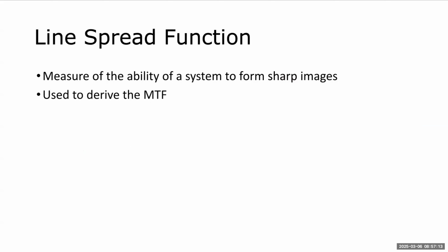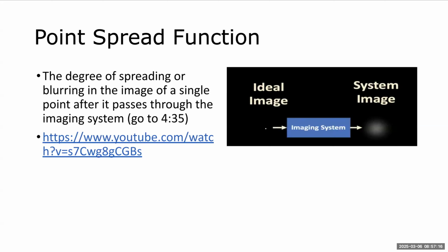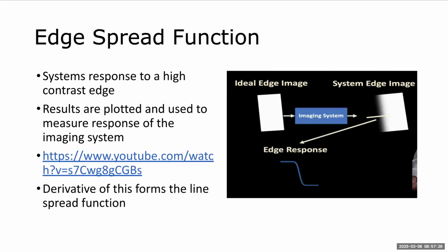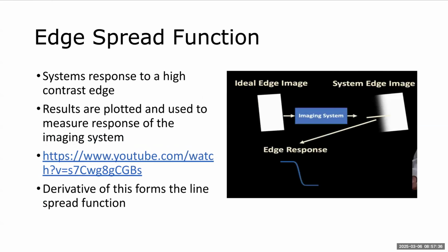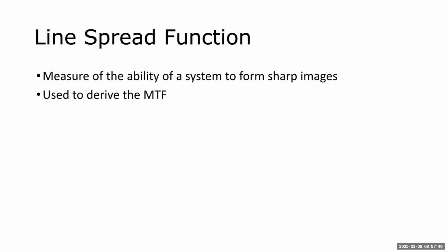Now, these next 3 slides are sort of dealing with the same thing. We're not going to get into a lot of detail about these, but what you really need to understand is whether you're talking about point spread function or edge spread function or line spread function, it's different ways to measure the ability of the system to form sharp images. So whether we're looking at one particular point, an entire edge, or a line,